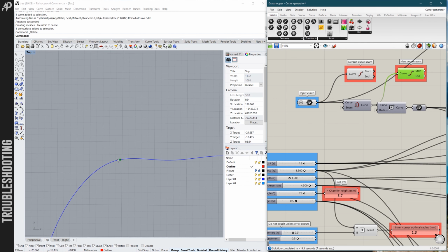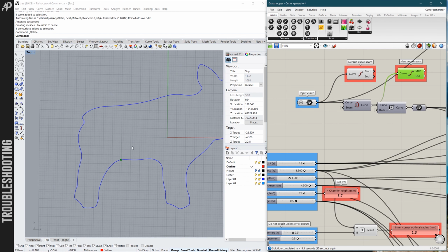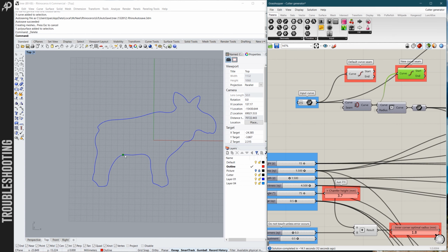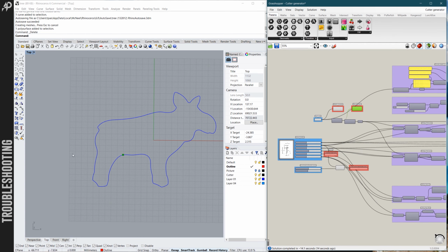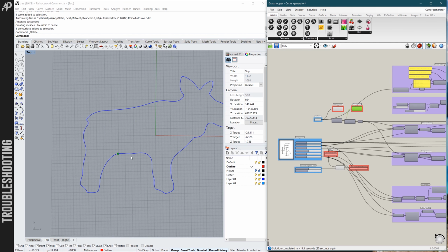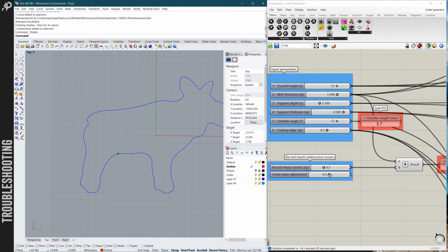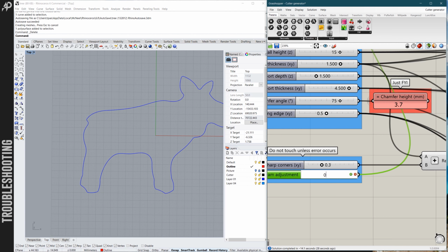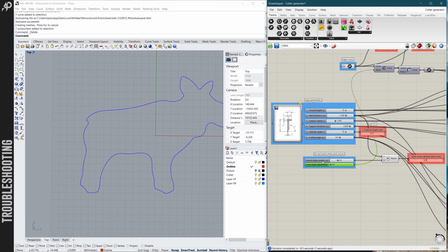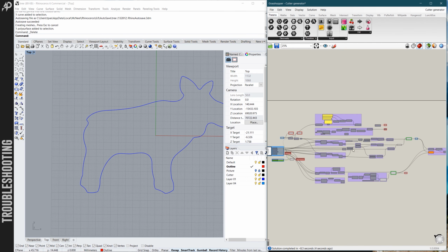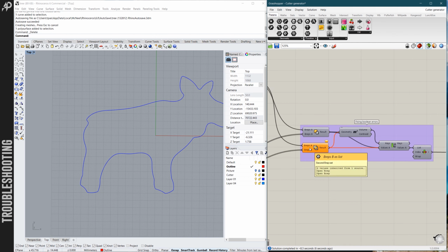And you can see that the position of our curve seam changed, and it sometimes might solve your problem. With this particular one, we didn't have to change it, but oh yeah, we did, because the default value was 0.3. We might as well check what happens when we let it 0. Let recompute. Does it still work? No, it doesn't.